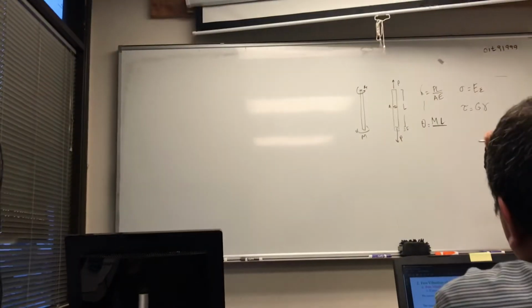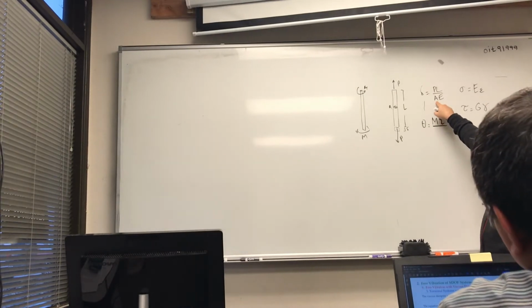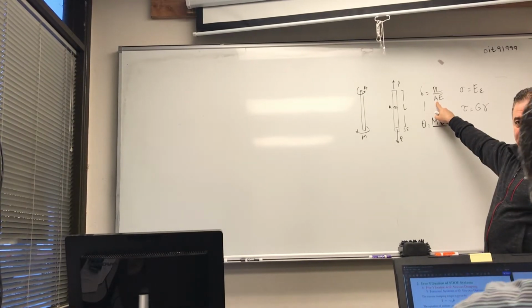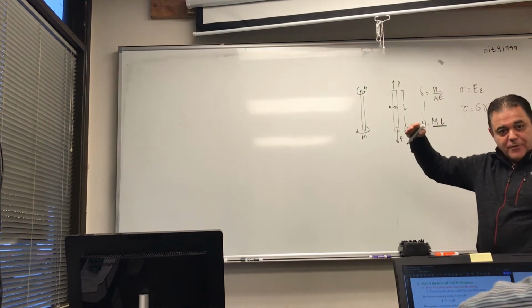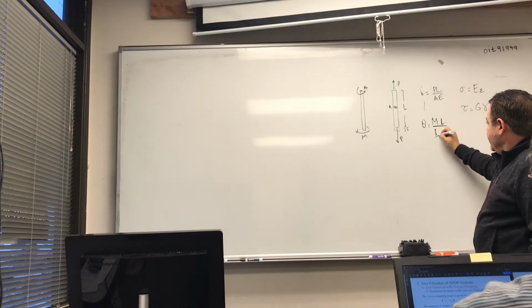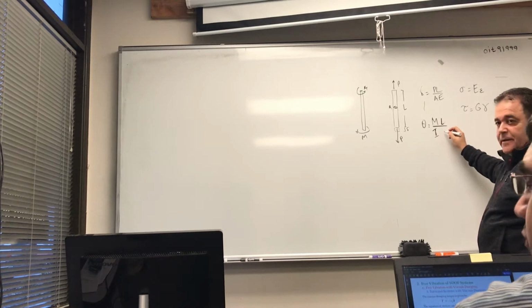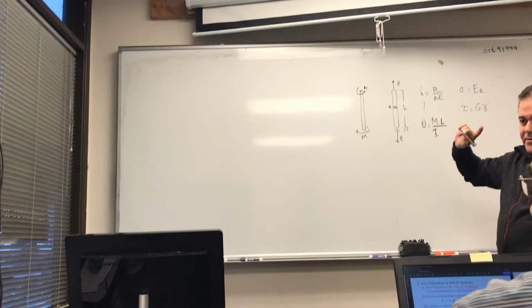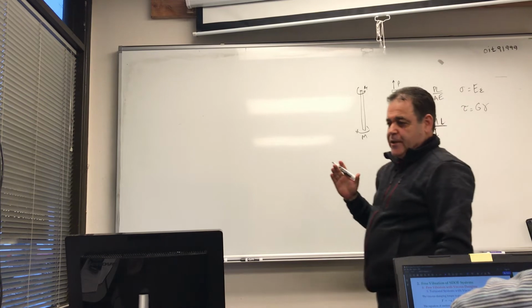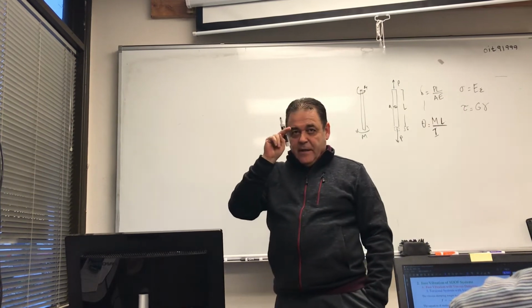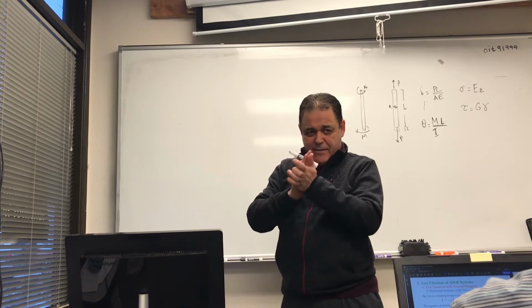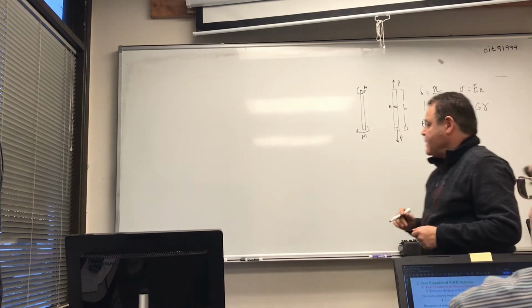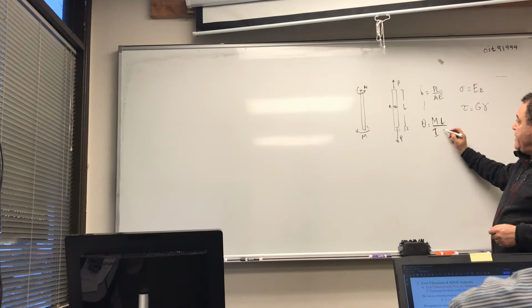Here it's not mass, it's area, so in rotation it will be the area moment of inertia, which is I. It's different from the mass moment. The area moment of inertia has a dimension of length to the power of 4. It's the stuff you do in bending and plane stuff. And then instead of E, it will be G.